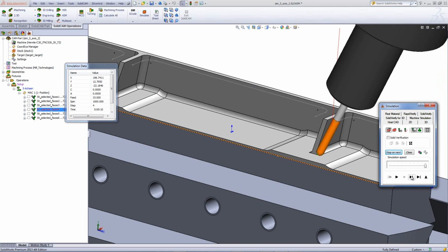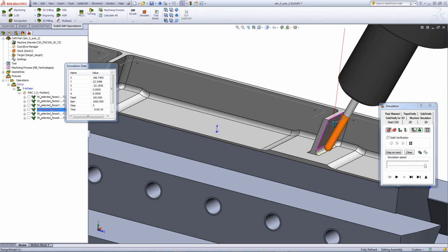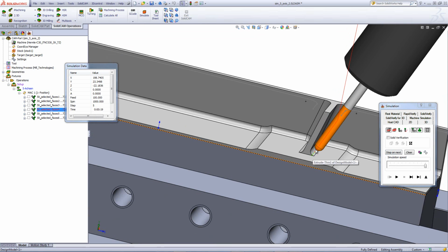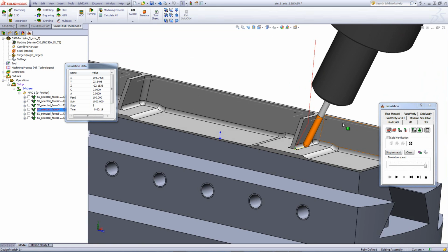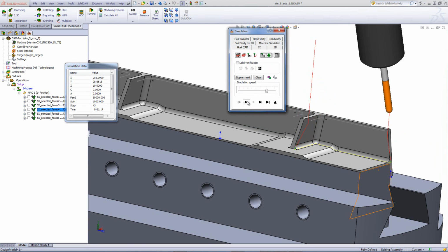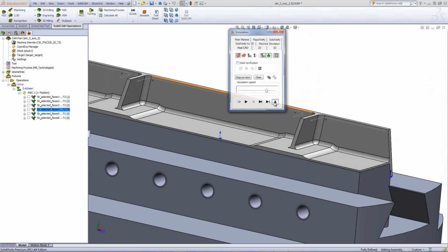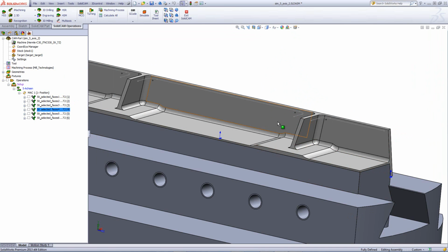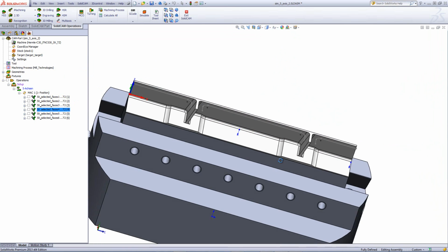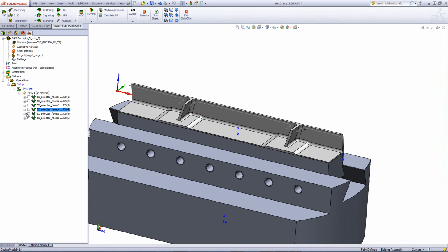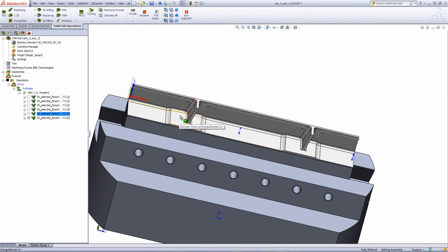down through that curve as shown over here, and the tool is on the radius itself, but not touching any part of the walls, making for a lot smoother cut on that surface as it goes around that entire area on the bottom as shown over there. Now, the same was done for these curves over here, for these radiuses on the bottom over here in this operation, and the same was done for the last operation over here using this curve over here.